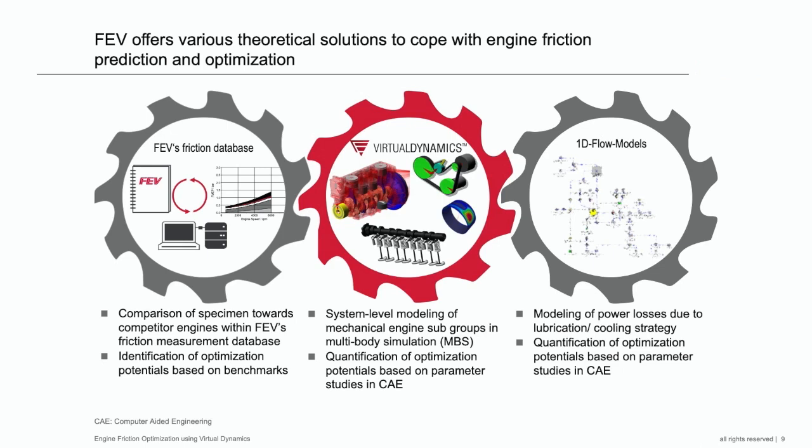On the right side, we have the capabilities to review the losses from the hydraulic system of an engine application using 1D simulation. And the gap between these hydraulic losses and the system level analysis is filled with the component level friction simulation using virtual dynamics.